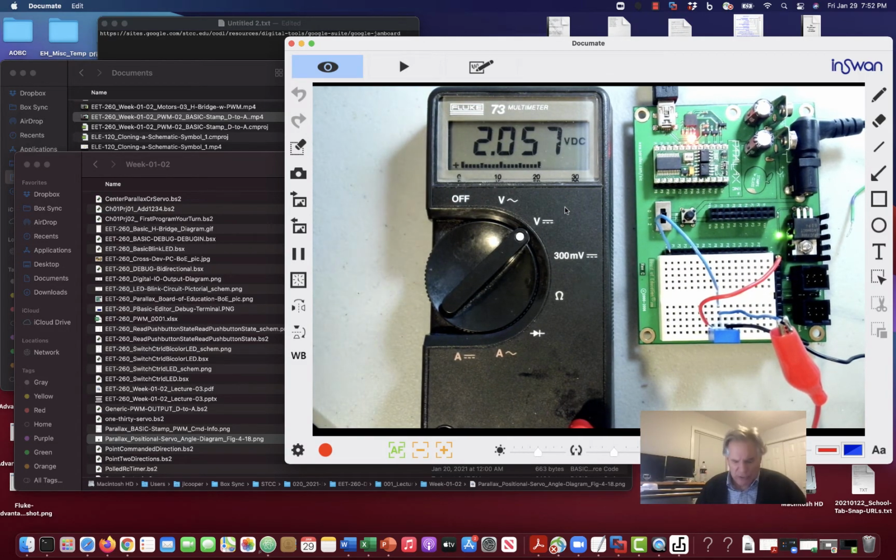And again, if you have some sort of trip mechanism like a voltage comparator, when your linearly climbing capacitor voltage is equal to or crosses over the voltage you want to measure, your microprocessor could have timed the start of that charging of the capacitor to when its voltage crossed over your voltage to be measured, and you do a little similar triangles thing there, and you can say, oh, I know what my voltage is because I know how long it took to climb up to that voltage with a constant slope increase in the voltage.